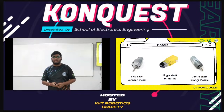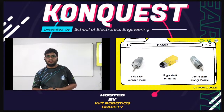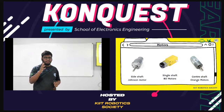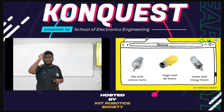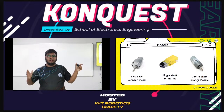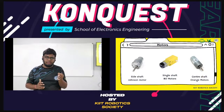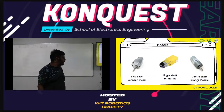So, what about the OG 555 motors? They have the base motor of RS775. It's a high RPM motor, with around 18,000 to 20,000 RPM and very little torque. For providing enough torque, they have added a reduction gearbox of around 2 to 3 centimeters, and they made a gear reduction to increase the torque. You can see in the presentation it is from the center shaft orange motor.